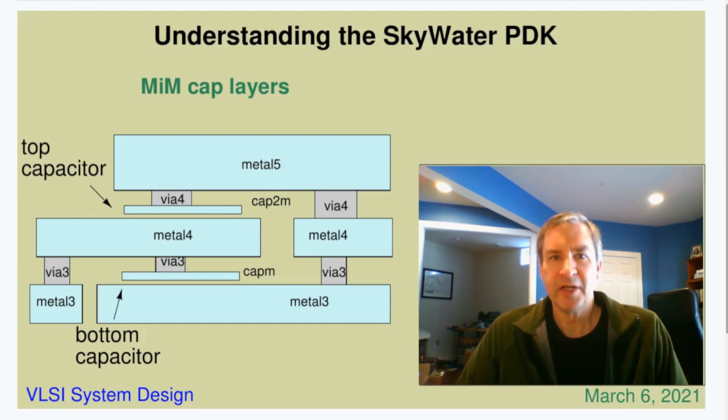The capacitors are particularly useful because by being fabricated up in the back-end layers, the area underneath them remains available for placing transistors and other front-end components.